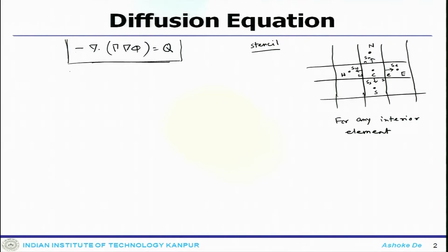All this SF are the surface normal vectors, where F goes from east, west, north, south, and also this two dimensional grid system is uniform. So, we had this delta x, similarly this one also delta y.